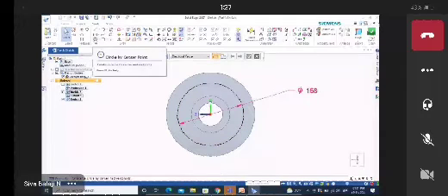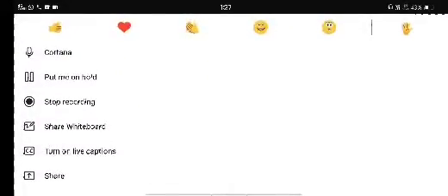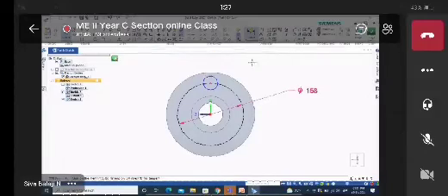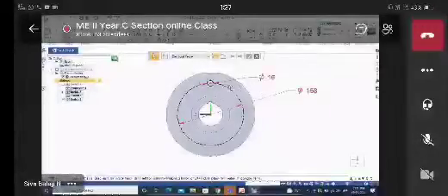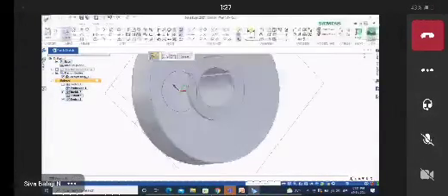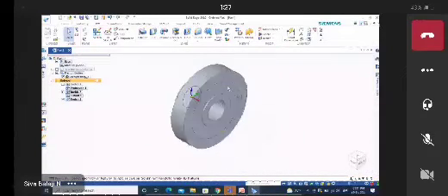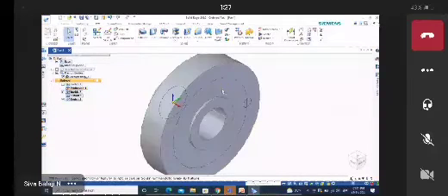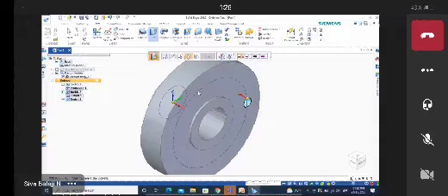Okay. Now you can select the circle command again, select the point, and draw one circle with a diameter of 16. It will get automatically constrained. After creating this circle, I want to cut this portion, so we can close the 2D sketch here. You can go to 3D. As per your convenience, you can do it like this, and select your cut command. Check whether cut from sketch is selected or not. After that, I want to create a hole here, so I selected this circle. Now you can accept that one and show the direction here.